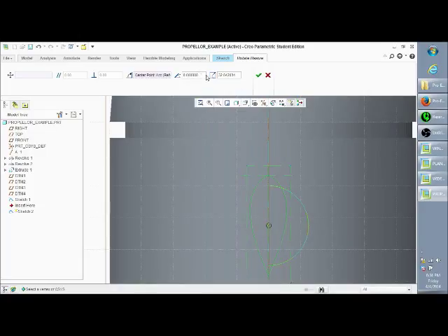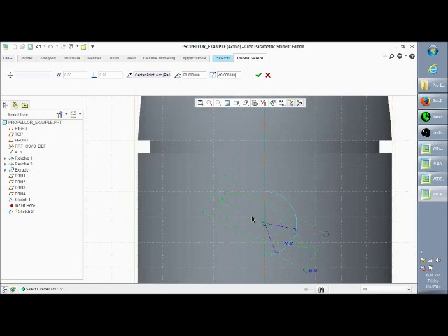So now what we want to do is set this rotate to, let me just double check. I want to set it to 60 degrees. And then we want to set the scale, which is this option right here, to 40. And since we created this shape on a basis of a 1-inch airfoil, it'll pretty much be saying that you're making the baseline, which is this right here, 40 inches.